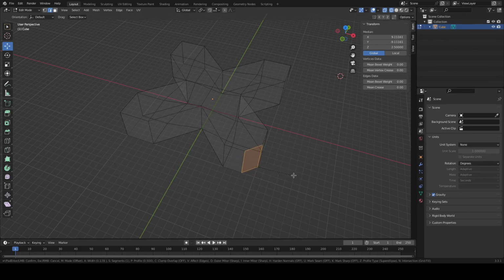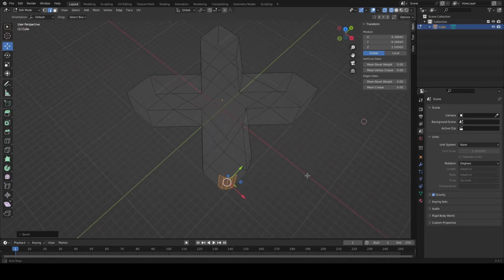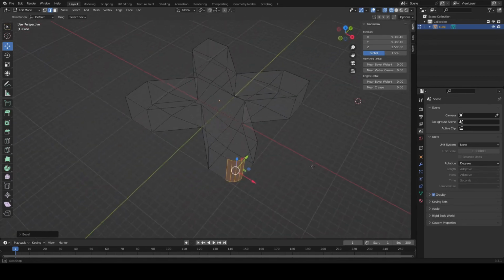And what's happening is that this is cutting off the edge of your square, of your X. And this will look better if we add more faces. So what I want you to do is I want you to push the scroll wheel on your mouse up, and when you do that, you get more faces on your bevel. And you don't want to add too many. Like 4 is fine, and you don't want to go all the way to the edge like that. Go about just a little ways in like this. So you can see I have a nice rounded edge to my X now.